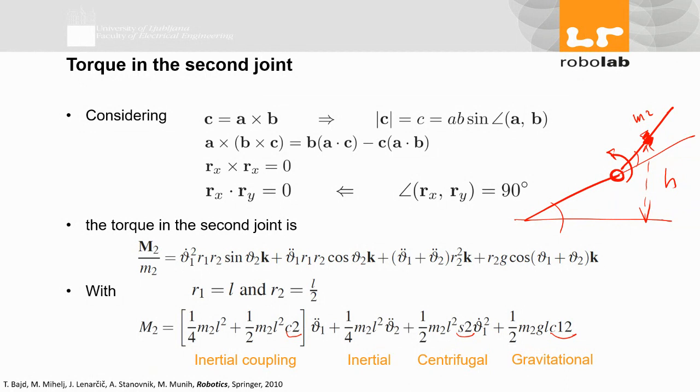But if I ask you, like in the test, does theta 1 have any effect on the torque you need at the second link of a 2-link robot? The answer is yes. And it's only for gravitational though, right? Exactly, and only on this part.